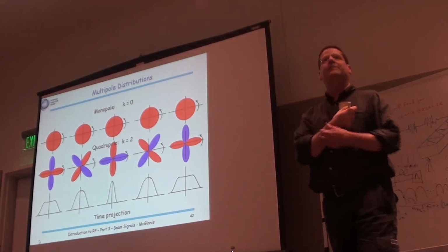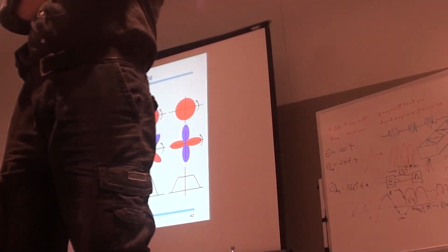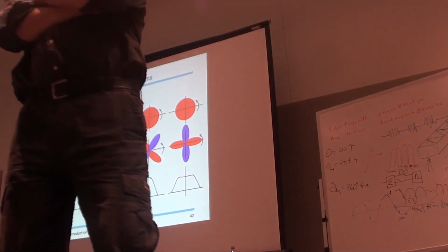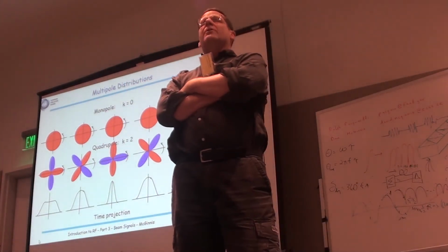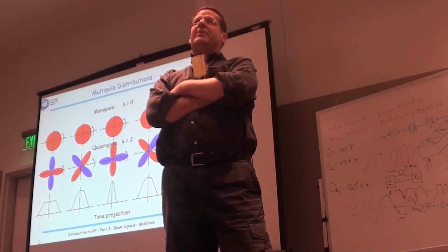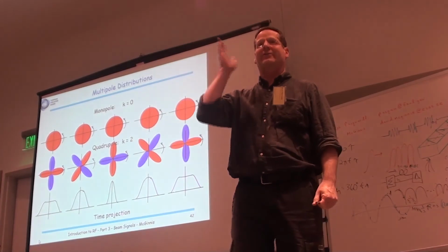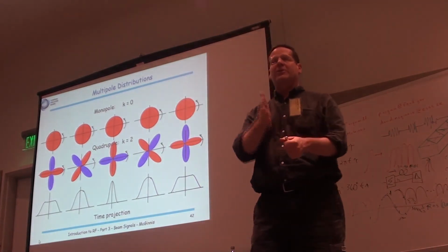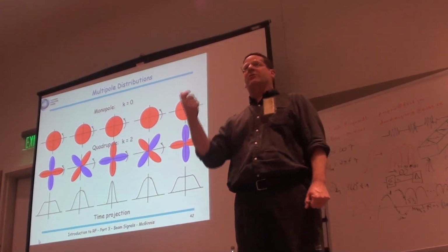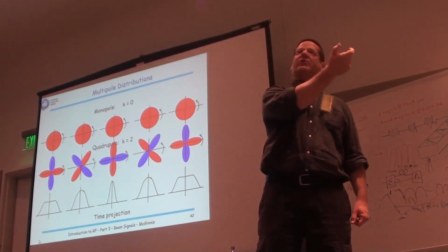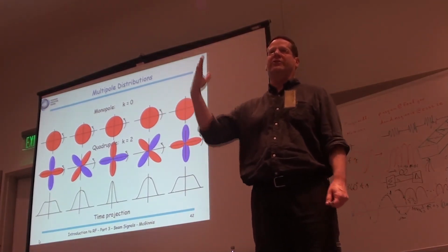Yeah? So, to re-observe the dipole oscillation, you have to move the observation point, right? No. To just see the shape moving back and forth, you have to have a trigger that's given by your RF frequency. So you know your RF, right? Yeah, that's the thing. So you take an oscilloscope and you trigger it on the revolution frequency. What you'll see on one turn is over here, on the next one, it's over here. It'll move. People build mountain range displays that are really cool. You'll see these things go back and forth like that.